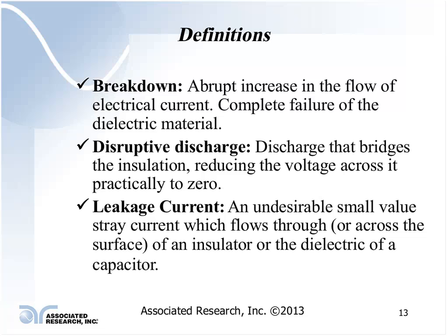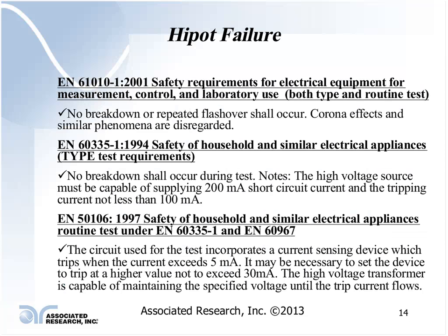When was the last time that I tested it and it worked properly? Well, I did it this morning. Now I can go back and look at every product that I produced from that point on, and retest it if I have to, once I make sure that my Hipot is working properly. So this is important, to make sure that you do a daily fail verification whenever you're doing a Hipot test.